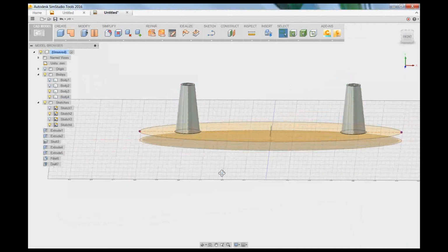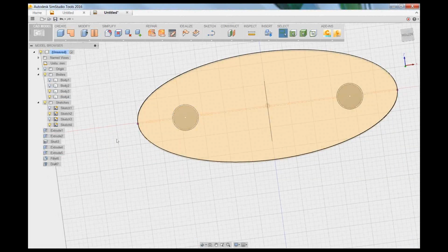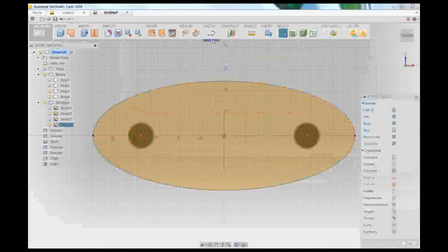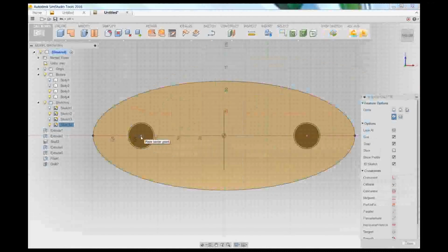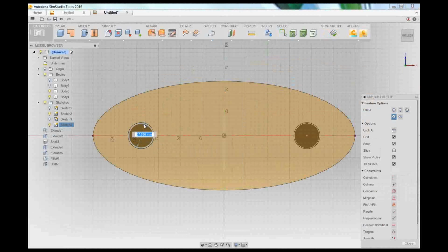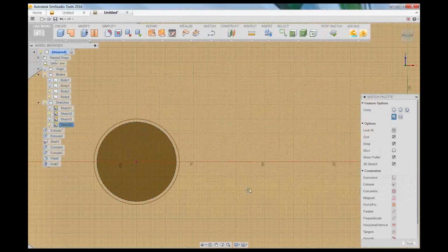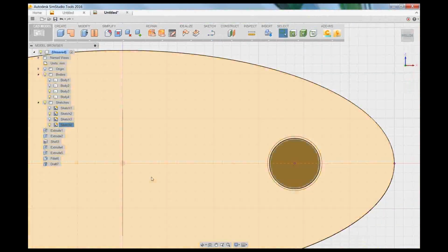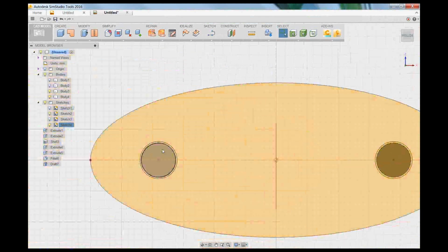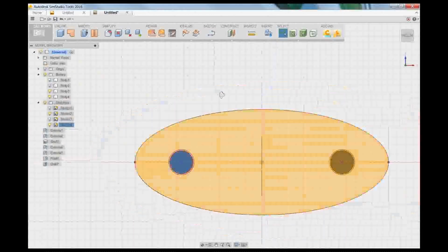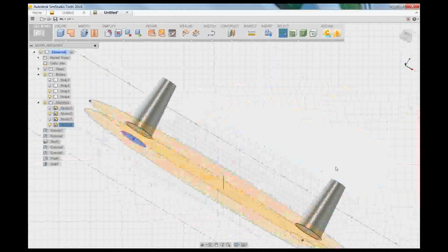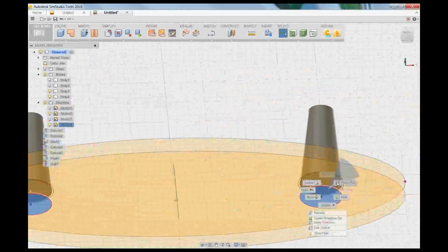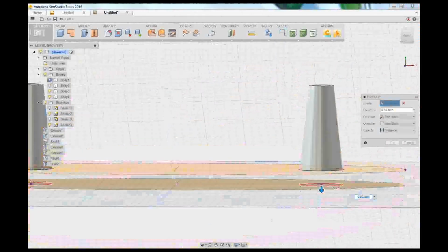So this kind of hints at what I was going at. As you can see, we're able to project that geometry on here. If I go into the sketch that I made and edit it, I can sketch some circles again. You'll notice I can still click that center point, but I can also snap to where the actual body edge is. And again, I'll close it and select. Now I'll be able to use the press pull again to cut through these bodies.